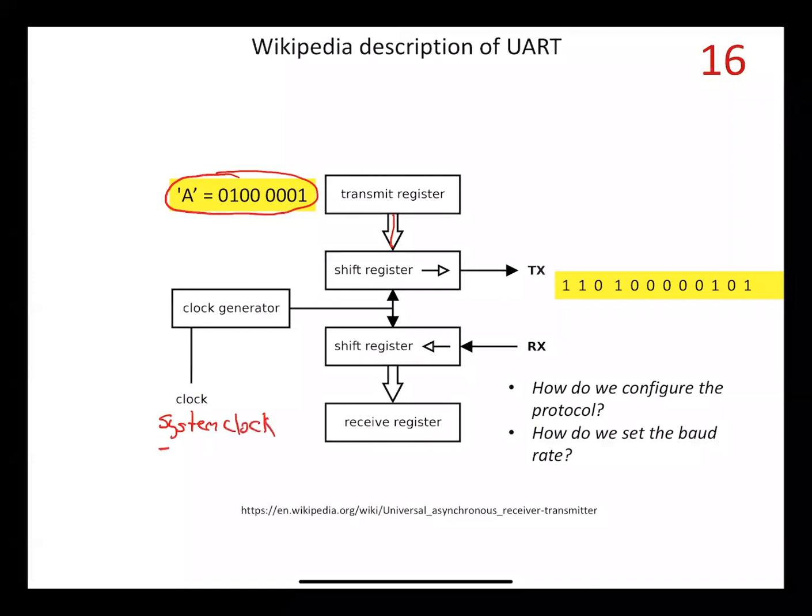And the system that you're dealing with, the frequency of that oscillator is 16 megahertz. Now we can use different clocks to set up the time base of an ATmega328P chip. The way the chip on the Arduino UNO is configured, it's configured to use an external clock, and there's a 16 megahertz clock that's hardwired to that, and that's on your Arduino UNO board.